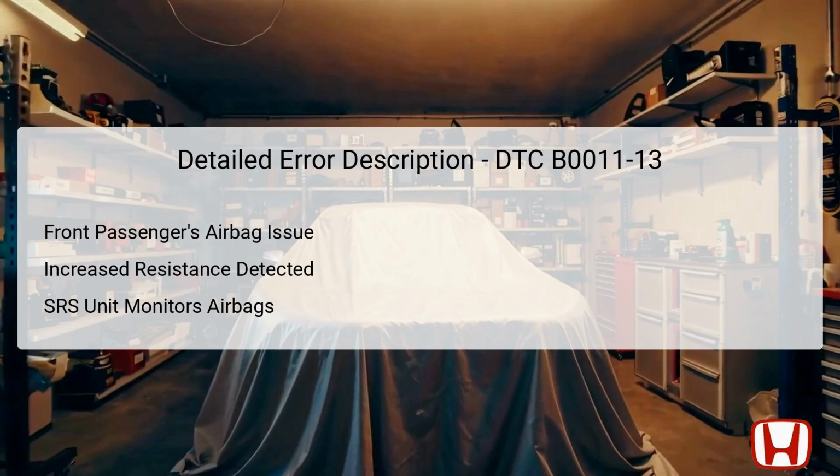This system involves several crucial components, including the inflator and the central SRS unit. The SRS unit, which is centrally located in the vehicle for optimal functionality, continuously monitors the airbag system for any irregularities. Its role is to ensure that the airbags deploy correctly during an accident to protect passengers. If an open circuit or excessive resistance is detected, the SRS unit registers this as an error and stores it as DTC